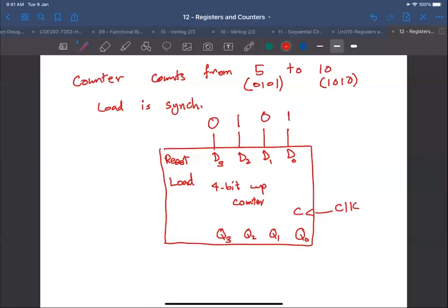Okay, so 10 is detected by ANDing these 2 bits, and I connect this to my load. So this will count. We assume that there is a transient period. The transient period, okay, you never know what is going to happen. So maybe you have what we call a preset input that will restart your counter.